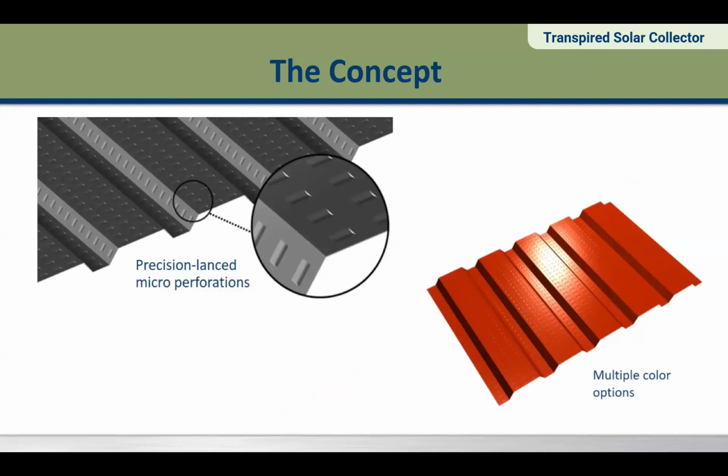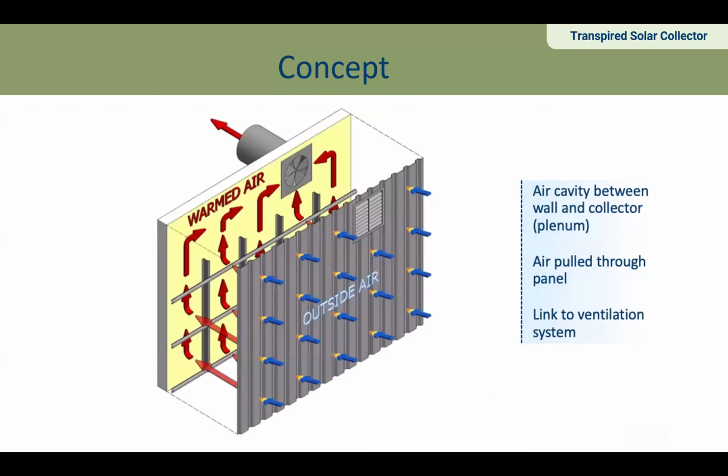And then I'll switch back to the previous slide because it's a better overall diagram. Instead of having that be a half inch to an inch off the insulation and vapor barrier, we're going to pull it off somewhere between 6 and 8 inches and create a big air plenum back there of superheated air that you can then draw directly into your HVAC system.